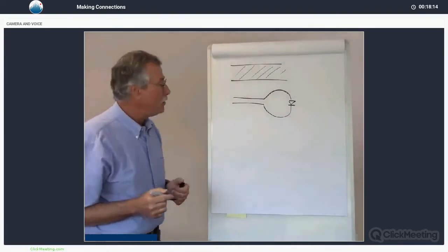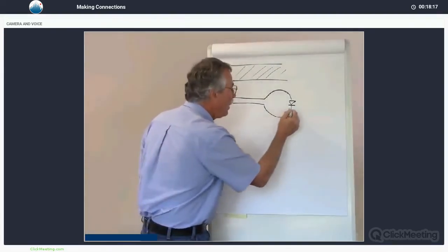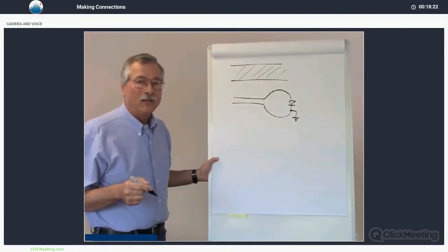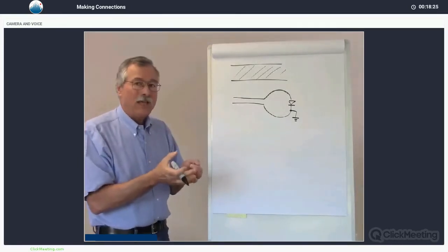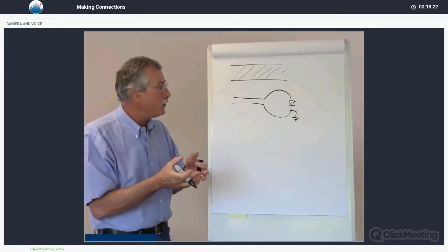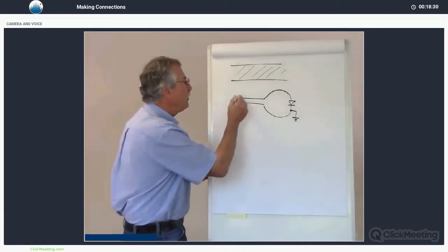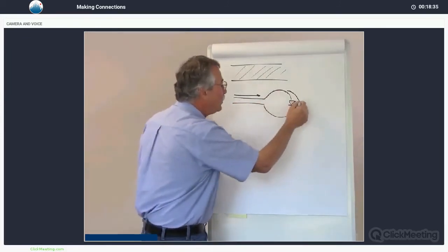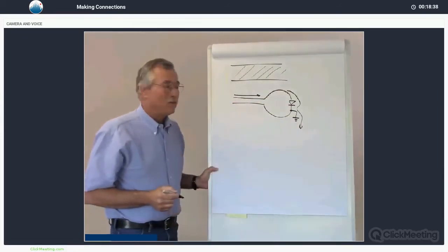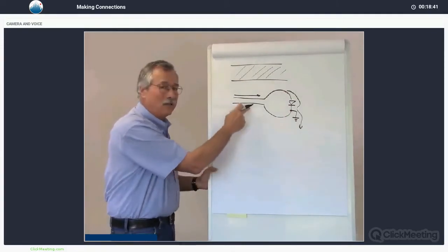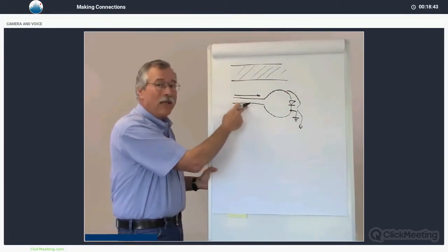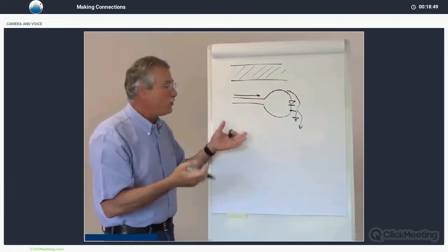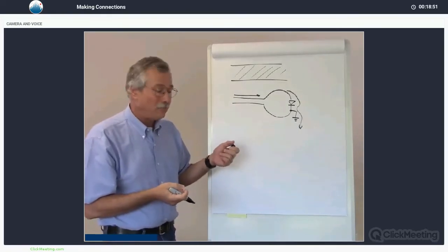There's something else we have to remember to not do, and that is we don't want to ground either the cathode or the anode of the laser diode. Sometimes the clamp arrangements on the table will do that. They will ground one side or the other, but now you can see what's happening. We're feeding current out to the laser diode through one conductor of the strip line, and it's returning to our laser driver through ground and not through this conductor. Obviously, the current is unbalanced. More current here, less current here. The magnetic fields will not cancel. We've just lost the reason for using strip line.